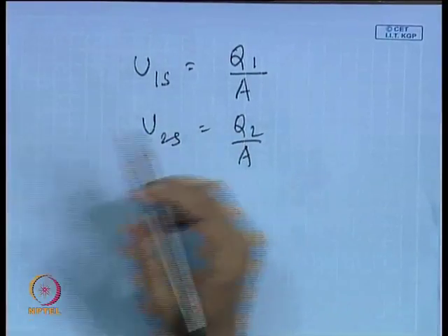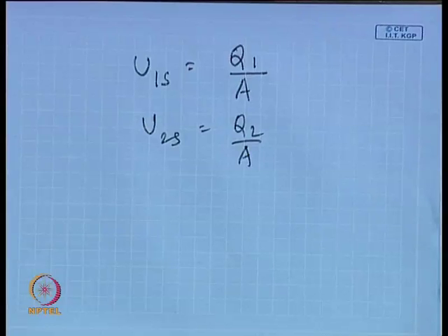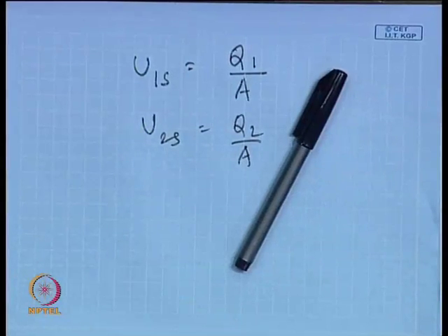These are not correct, so please keep them in mind. So, these are the actual definitions. Therefore, whenever we refer to a fluid in two-phase flow, you will find in several journals and textbooks that they mention the velocity of fluids. Please remember, the velocities they mention are the superficial velocities. We come across the superficial velocities.